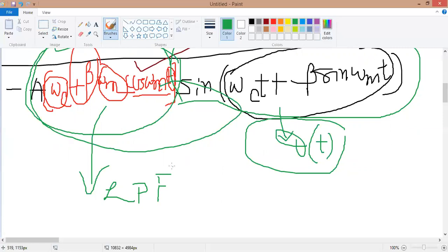But then how do I say the amplitude modulation is most important? It is most important in this sense: I want to pass it through the envelope detector, and then the low frequency message can be found, and that message can be passed through the low pass filter to obtain the original smooth message back, because all the high frequency terms and undesired components are removed. So this is the fundamental thing.